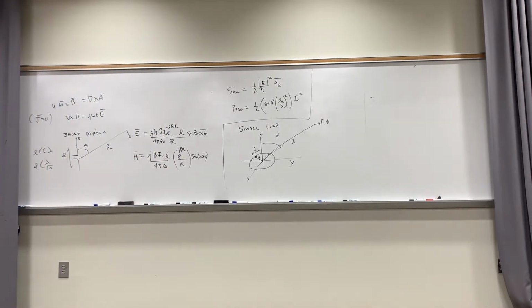That's the way you can always do these polarization tests. If you've got, say, a half-wave dipole antenna and you're holding it, and you've got a polarization filter there, whether I rotate that filter, or rotate this horn and the antenna while holding the polarized filter steady, I will see a peak power and then no power.